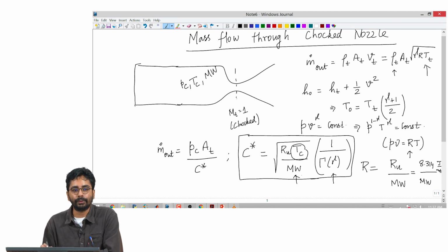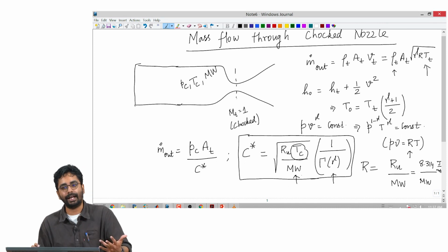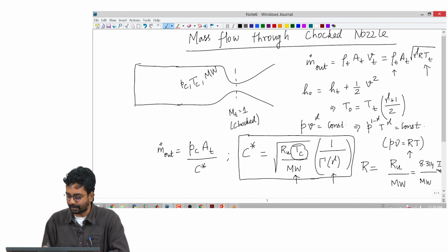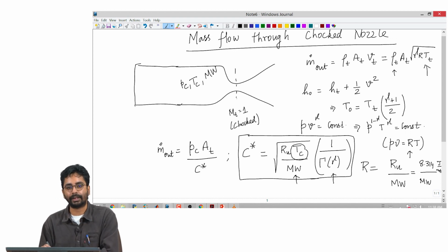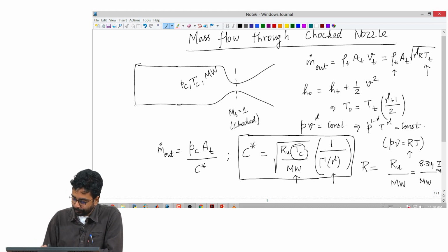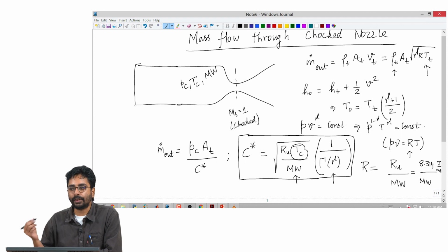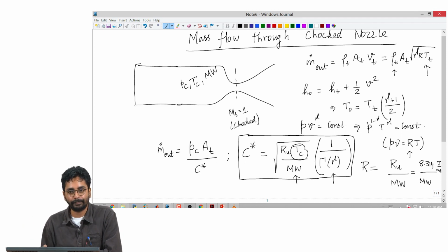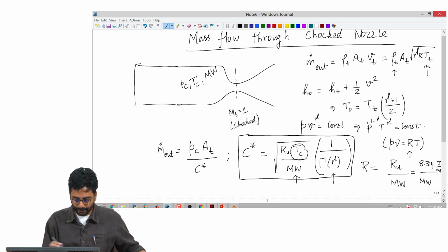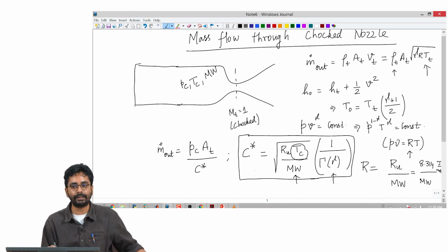Okay. So, the reason why, in the hydrogen oxygen system, the C star peaks at hydrogen rich conditions is because the molecular weight of hydrogen is 2 grams per mole, and therefore the value of C star, even though the temperatures are lower than under stoichiometric conditions, is much higher because there is a lot of hydrogen available. Okay. So, C star peaks under rich conditions even though the maximum temperature is close to stoichiometric. Okay. So, C star is a fundamental thermodynamic property of the propellant composition.